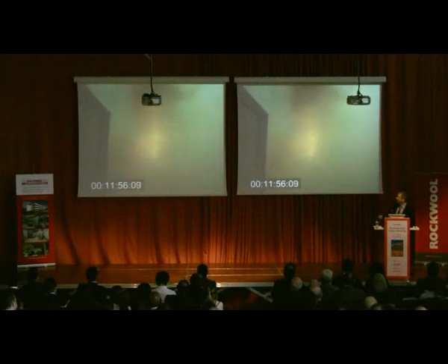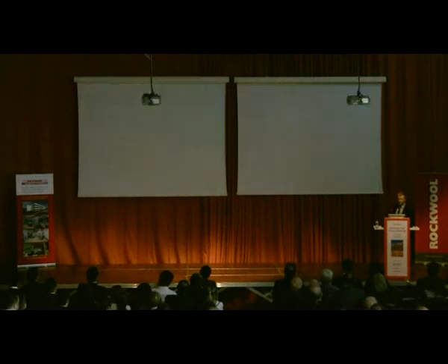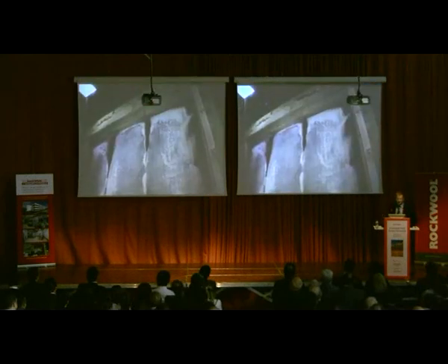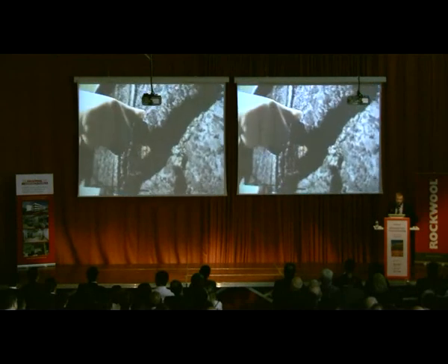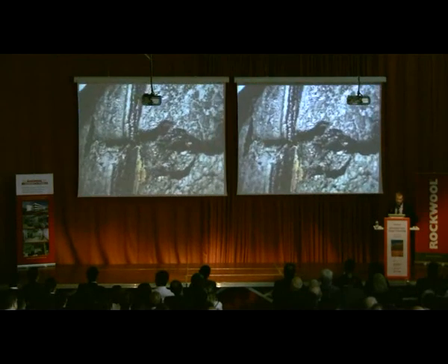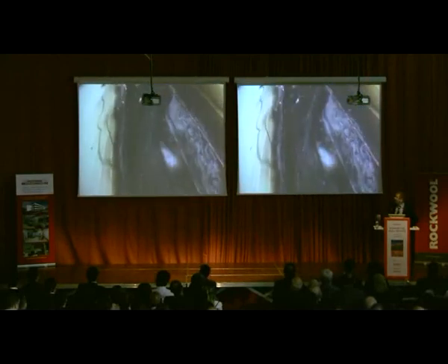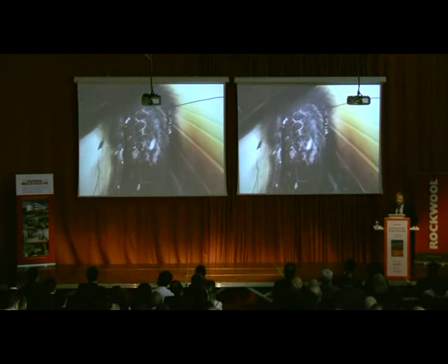And a failure happened shortly before 12 minutes. But it was only after this very long period of intense development of smoke. Of course, it was forbidden to go inside the test hall because this might be highly toxic gases. So you can see that even the laboratory technicians were only able to enter this hall only with breathing equipment. And this is what remains of the insulation core after the end of the test. This panel is classified as B reaction to fire class as well.